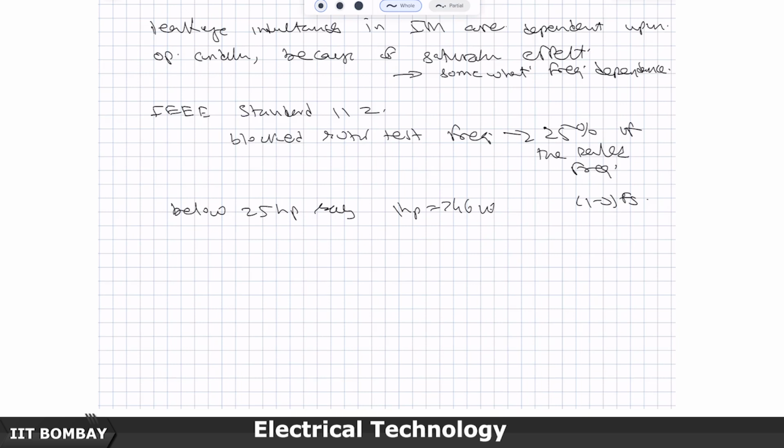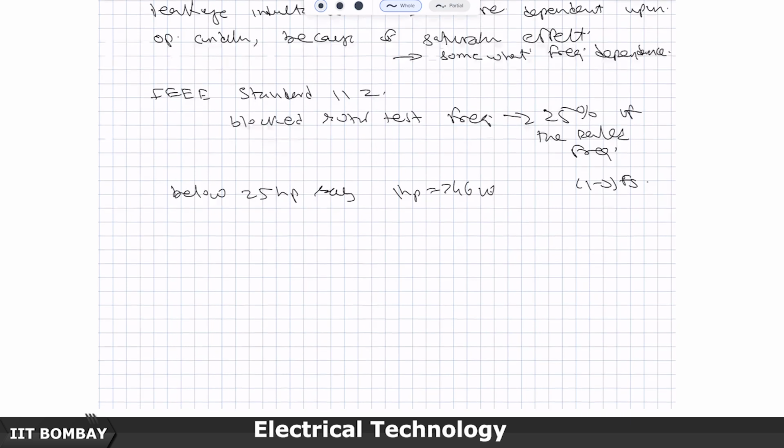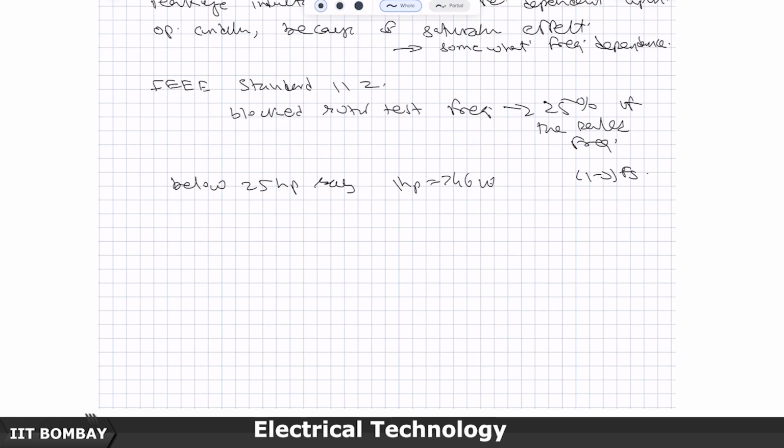Or if you are trying to get these parameters close to your operating condition, then the starting current is much higher. Starting current is much higher than the rated current, because the slip is reduced during the rated operating condition. So, reduce also the voltage, not only frequency, but also the voltage which you are applying to the terminals of the motor. So, let us say that V1BL